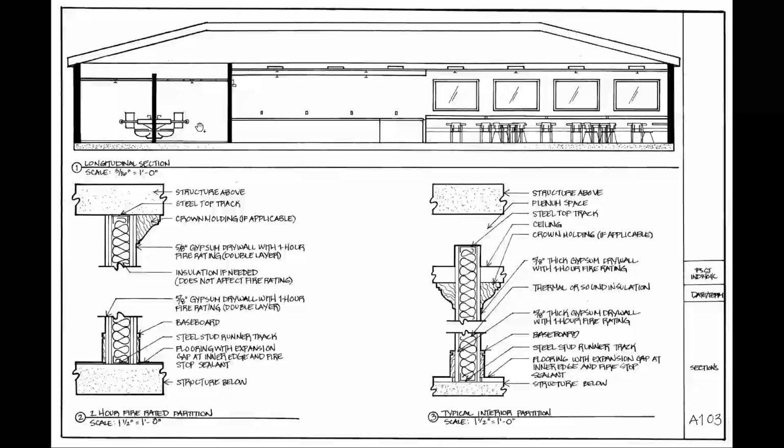So if a fire were to occur in this bathroom, it's going to catch on fire. Hopefully the smoke alarms start blaring and the sprinklers pop out and start spraying water. But if not, for whatever reason, the fire is going to go up here, it's going to go over here, and it's going to fill this room with fire and smoke. Okay, so this does not compartmentalize fire, but it's cheaper and it's not really necessary because the likelihood that there's going to be a fire in the bathroom is very small. So that's the big difference structurally between these two.